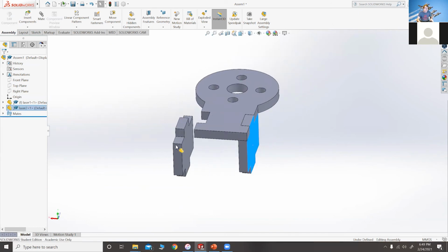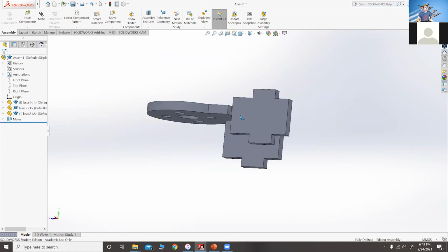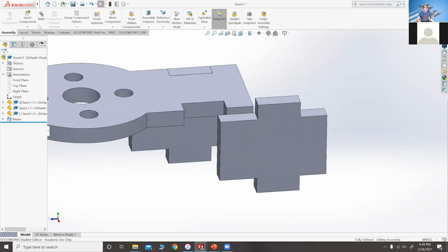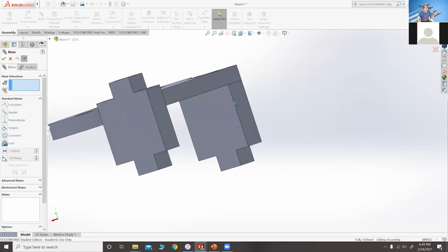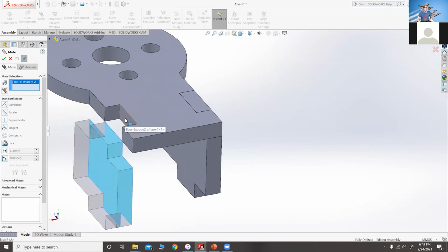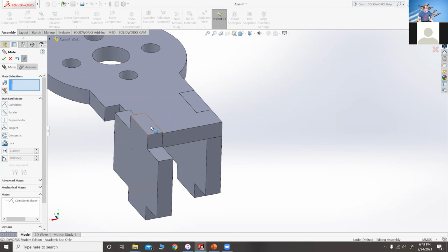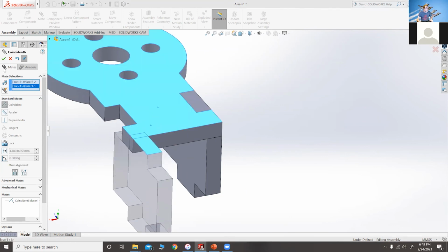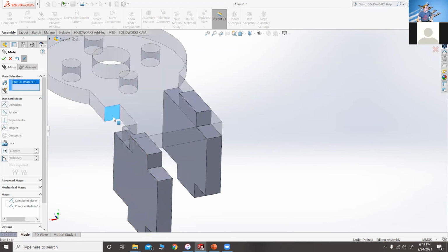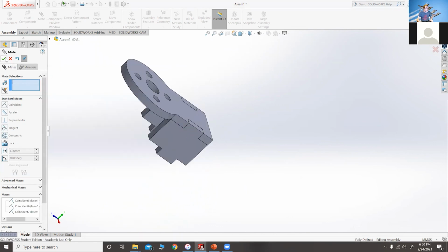If I Control-click and drag the part, it just creates a copy. That's a little shortcut in SolidWorks. It's pretty handy in big assemblies. I'm going to quickly mate this second one up, following the same deal. SolidWorks is pretty smart. It'll auto select the right mate, but if we don't want that mate, we can select a different type. All of them are just coincident. We want them to be touching. And now this part is fully defined.